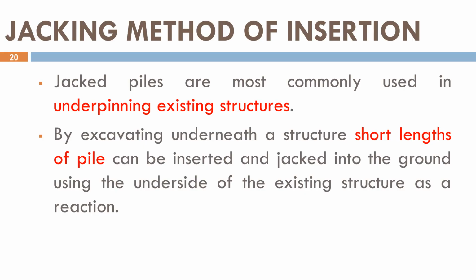Since no hammering is involved, this method produces almost no vibration and very little noise. For this reason, jacked piles are commonly used for underpinning existing buildings and strengthening old foundations. It is particularly useful in congested urban areas where vibration could damage nearby buildings.